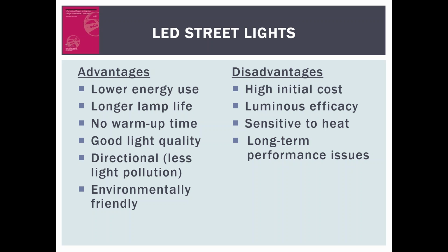While LEDs may last several years longer than high-pressure sodium and metal halide lights, they are sensitive to heat. For every 30 degrees above 70 degrees Fahrenheit, LEDs will lose half of their service life. This is especially an important concern in the south and southwest, in the desert areas. If a photocell is not working properly, a light may be activating during the heat of the day and significantly shortening the life of the LED lamp or killing it. However, major cities such as New York, Los Angeles, Seattle, Boston, and Phoenix all committed to convert all of their existing streetlights to LED streetlights.